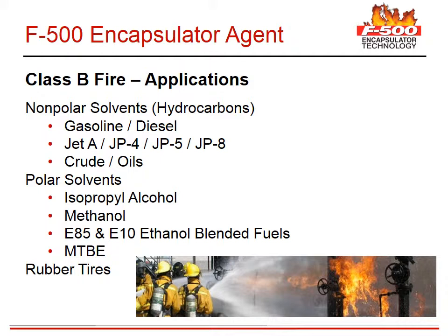This slide shows 2 different types of flammable liquids, polar and nonpolar. Hydrocarbons are nonpolar and do not mix with water, where polar solvents such as alcohol are soluble in water. F500 can be used on both types of Class B fuels using the same nozzle techniques. Different foams would be needed to handle Class B polar and nonpolar.